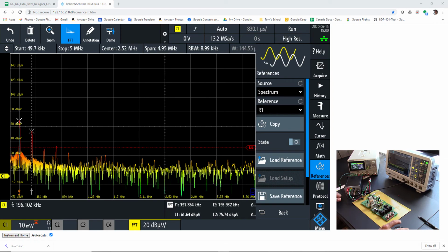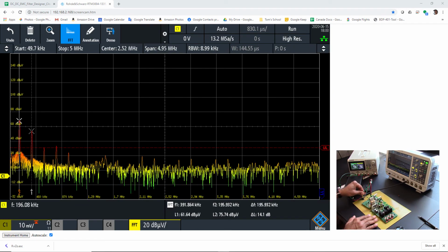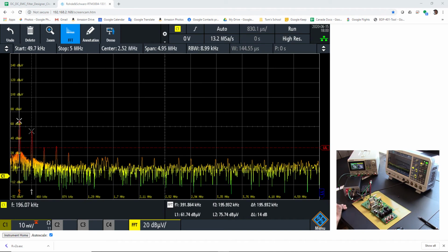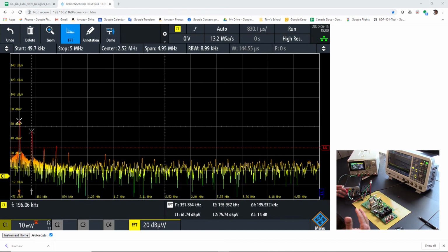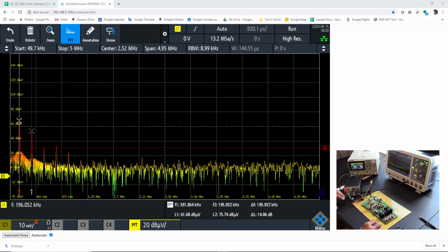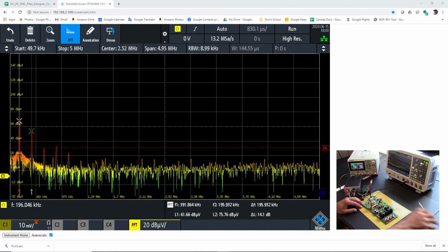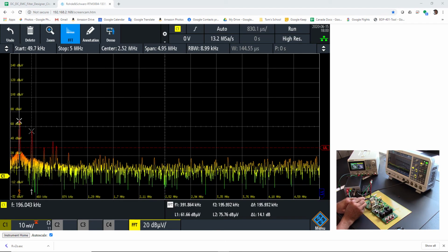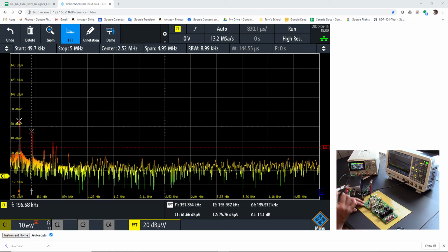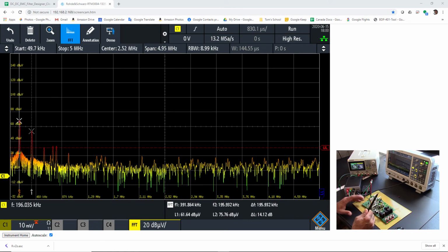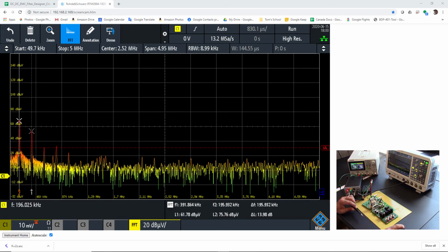One of them is, of course, that this is not an ideal setup. My ground plane is not nicely coupled. The ground plane of the LISN is again not nicely coupled. Now, in a real setup, on a real power supply, this will be integrated into the power supply. I've got dangly wires between the filter and the power supply. This is for teaching purposes and how you go about designing filters. But of course, when it becomes a product, all of these will be soldered on board of this converter.